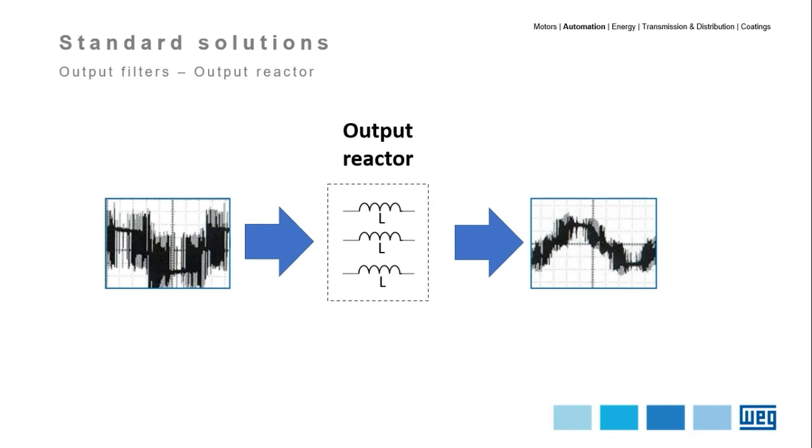The first one is the three-phase reactor, which is basically an inductor connected in series between two voltage points in the system. The reactor has an internal impedance capable of reducing line voltage distortion and reducing current peaks on the bus, once the current does not undergo sudden variations in an inductor. Another name for it is load reactor.